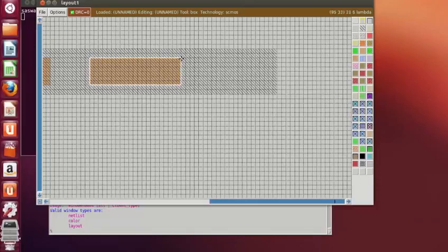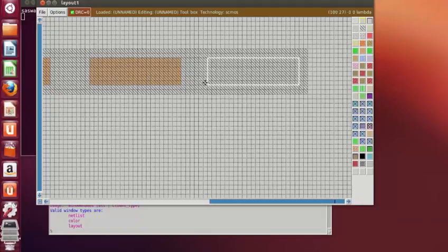Then select the same area. So still it's not sufficient, so we have to extend. Then middle click on N well. So I have this common area. And then middle click on P diffusion.